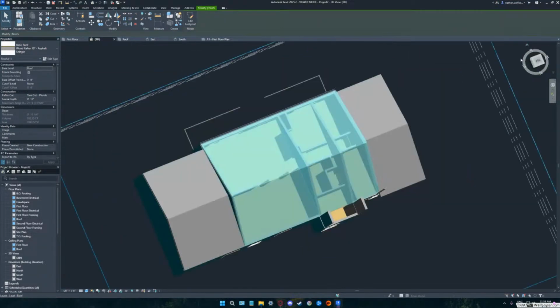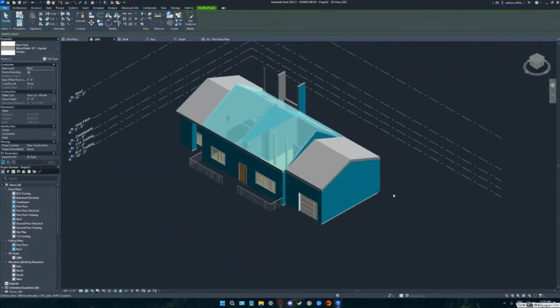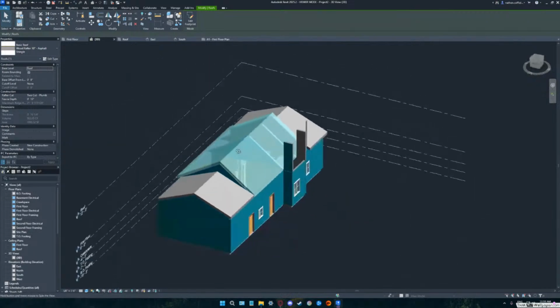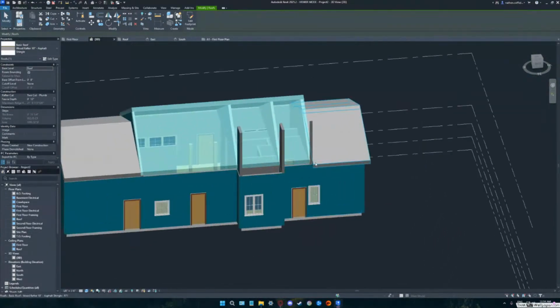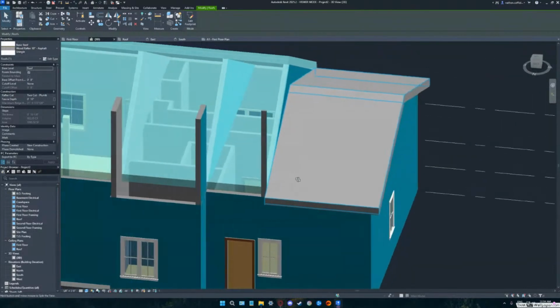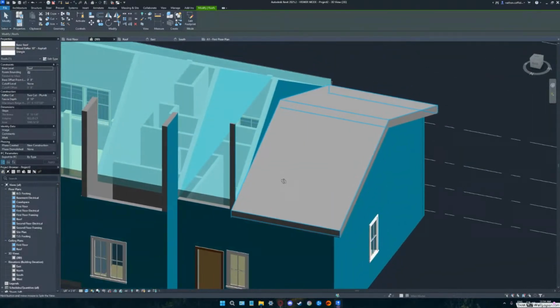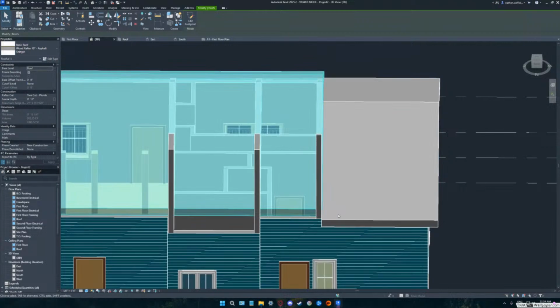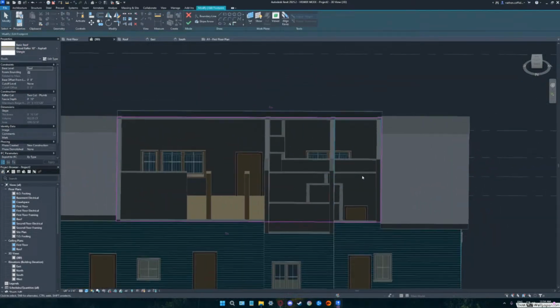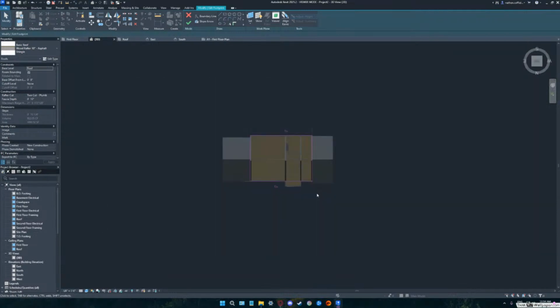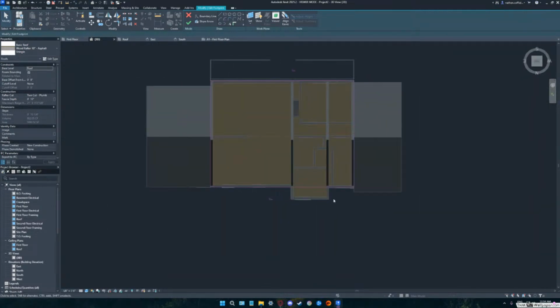Now, orbit your view up a little bit, and you need another little roof just over those punched out guys. Okay. What happened there? Well, that's because that overhang wasn't quite enough. So if you edit that footprint, remember you were going to offset all those by like 1 foot. Yeah. Double click on it to go into edit mode. Look at it from the top view. Use your offset command.